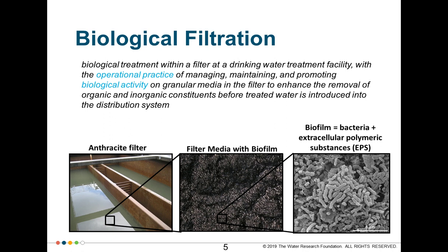To start off the presentation, I'd like to cover the definition of biological filtration that was developed by the AWWA Biological Drinking Water Treatment Committee. They define biofiltration as filtration with the operational practice of managing, maintaining, and promoting biological activity on granular media in the filter for enhancing removal of organic and inorganic constituents before treated water goes to the distribution system. So biofiltration is not a new technology, but rather an operational practice of filtration where we're intending to enhance the biological removal processes occurring within the filter.